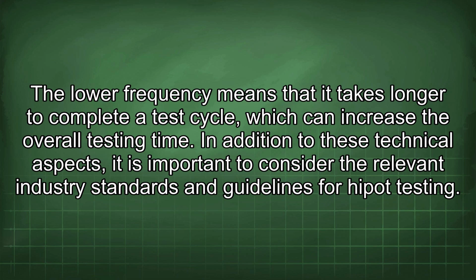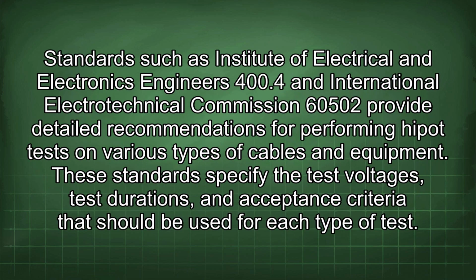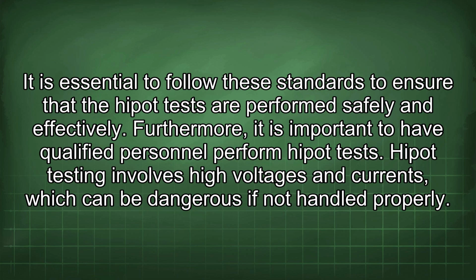In addition to these technical aspects, it is important to consider the relevant industry standards and guidelines for Hipot testing. Standards such as Institute of Electrical and Electronics Engineers 400.4 and International Electrotechnical Commission 60502 provide detailed recommendations for performing Hipot tests on various types of cables and equipment. These standards specify the test voltages, test durations, and acceptance criteria that should be used for each type of test. It is essential to follow these standards to ensure that the Hipot tests are performed safely and effectively.